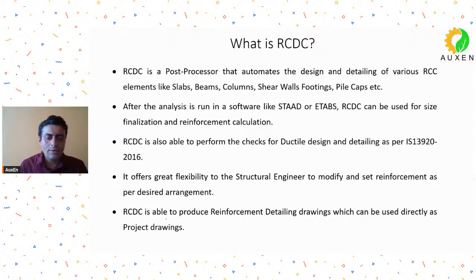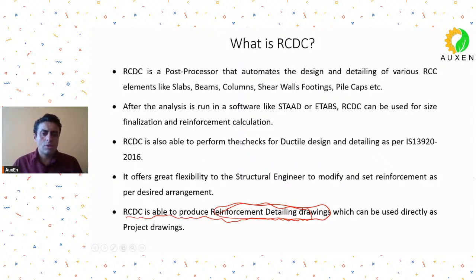So as I was telling you, another important feature of RCDC is that it is able to produce very good reinforcement detailing drawings. Okay, so based on the detailing that you have finalized, the detailing that you have proposed, on the basis of that detailing, as per the codal provisions, obviously it will generate to-the-scale drawings for you, which I have seen many people use directly as part of their project drawings.